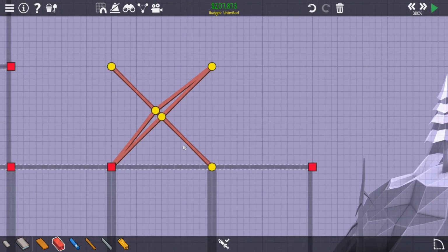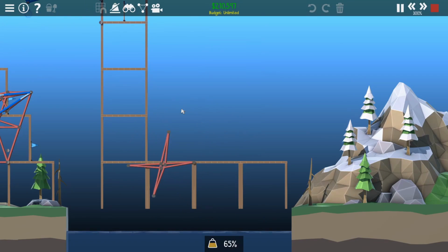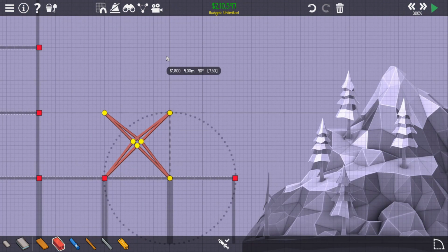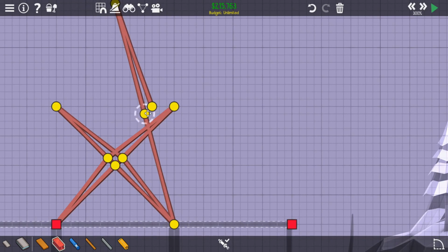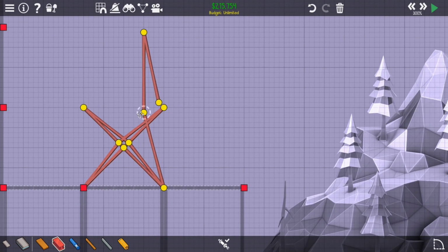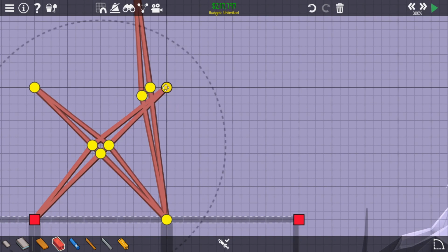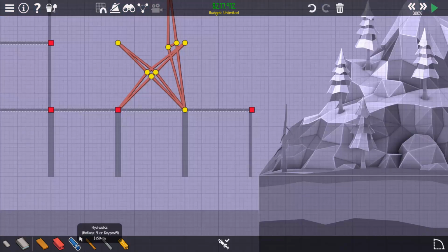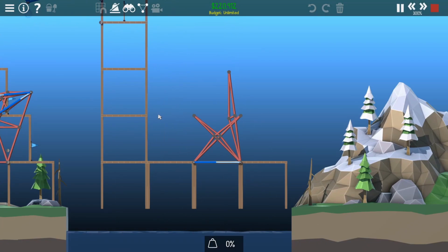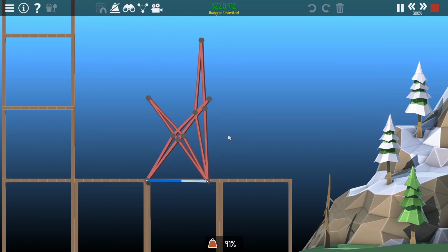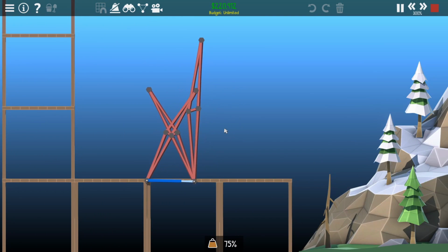It's going to be a scissor mechanism, and I've seen these before, but I've never actually been able to use one myself. And they actually work, they're pretty simple. One of the legs is going to be fixed jointed to the platform setup, and the other leg is going to be on some sort of slider mechanism. Now I'm using an arm here as a linear approximation mechanism, so it can slide side to side. It does dip down a little bit because it's tracing the arc of the circle, but I'm using such a small piece of the arc that it ends up being effectively linear.